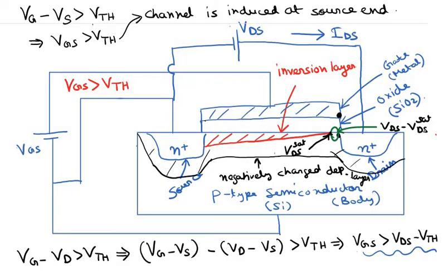Once this channel becomes pinched off, just remember that the voltage at the point at which the channel has just pinched off does not increase with increased VDS.